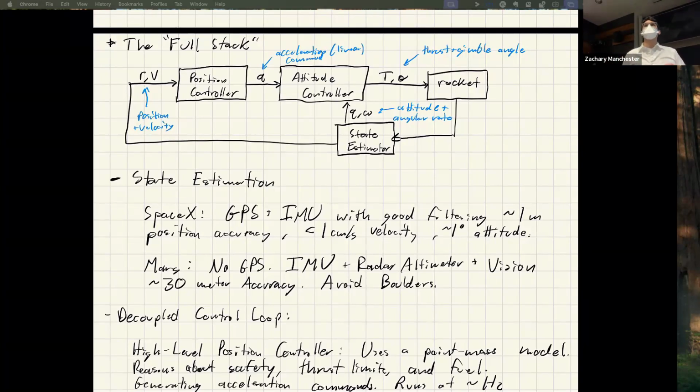It's really easy to get an infeasible problem instance or converge to a bad local optimum, this kind of stuff. And if it's an online real-time application, you really want that problem to be convex, because you want to be able to guarantee that your solver is going to converge within 10 milliseconds or whatever, and give you the answer that you can stick on the actuators. So there's kind of two pieces. It's both a compute thing and a guarantee thing.